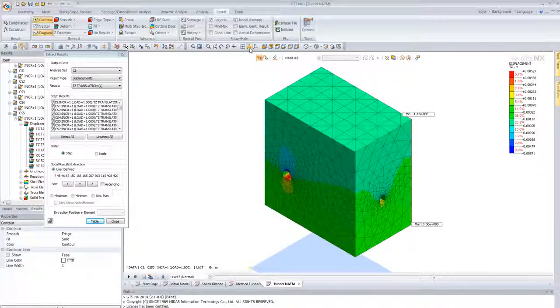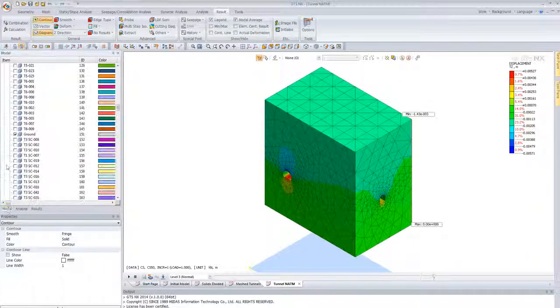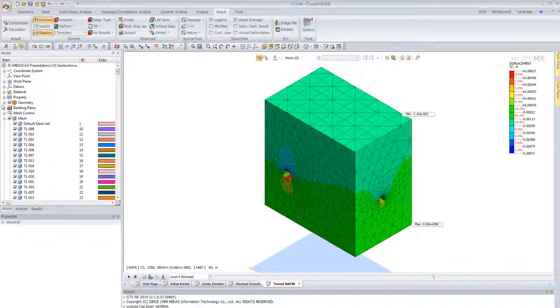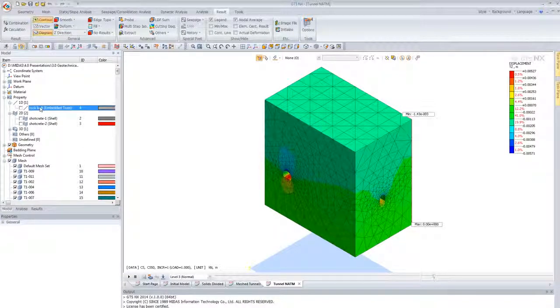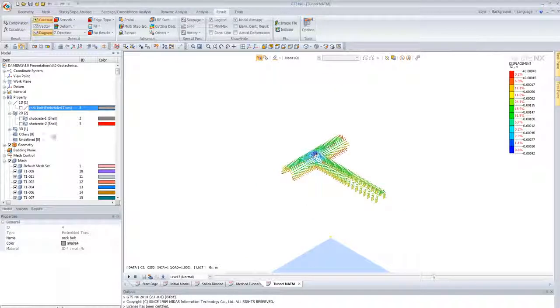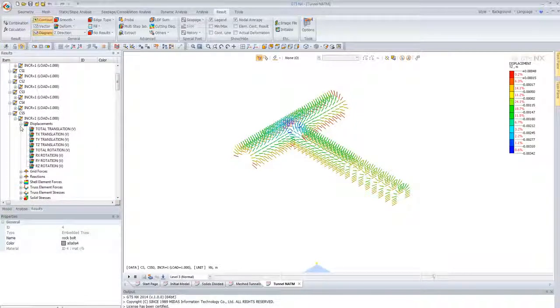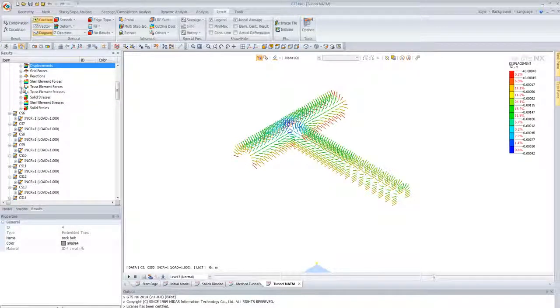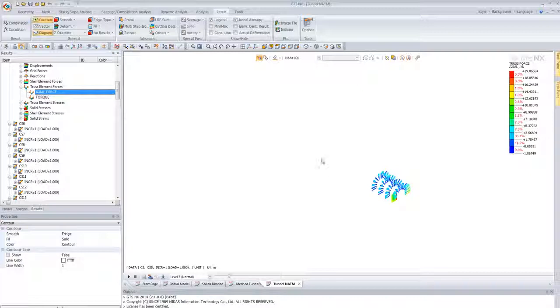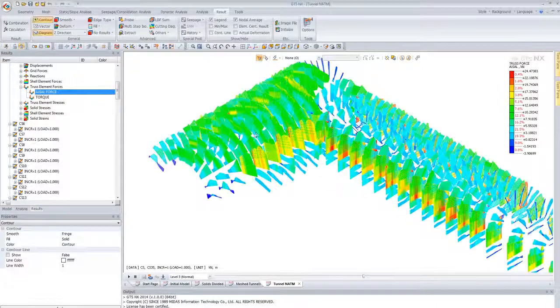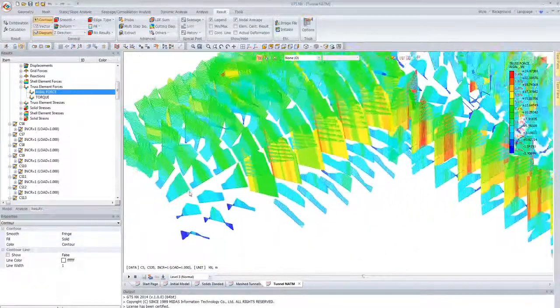Go back in. And I just want to show you the rock bolts. So just select the rock bolts and the mesh. So just to show only these. There we go. And I've isolated the rock bolts. You just want to see the forces results. So I just want to go down to the bottom. So for the truss element, so the actual forces, I can see that going throughout the different construction stages as well. All the connecting galleries there, and the stresses.